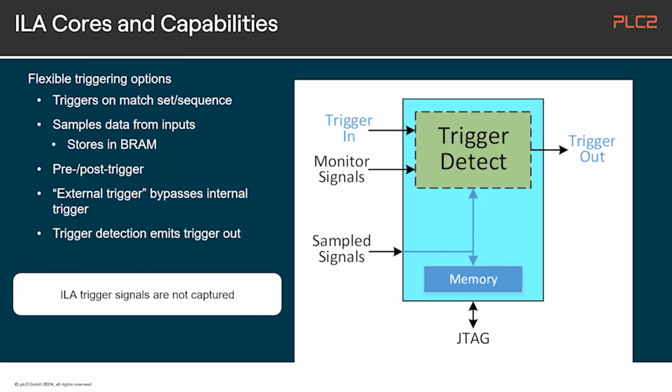The capability of cross-triggering requires trigger signals. So here we are quite flexible when we see that optionally trigger signals can be enabled on the external side or can be enabled with the ILA internally. The blue signals here are shown as optional extensions, but with the probe signals you use, you can by default even use these sample signals also for triggering.